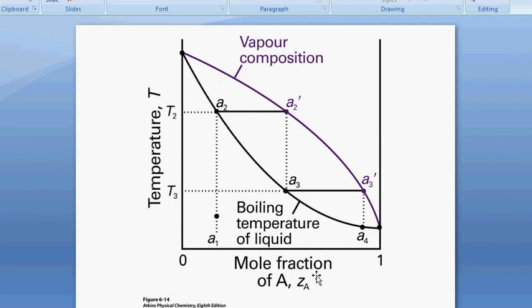So now, this is inverted. Over there we had higher pressure was liquid, here lower temperature is liquid. So the bottom part is liquid, the top part is vapor. Now, in general the boiling point would change as a function of composition this way, if the two liquids are not interacting. If they are interacting, then we'll come to that example also.